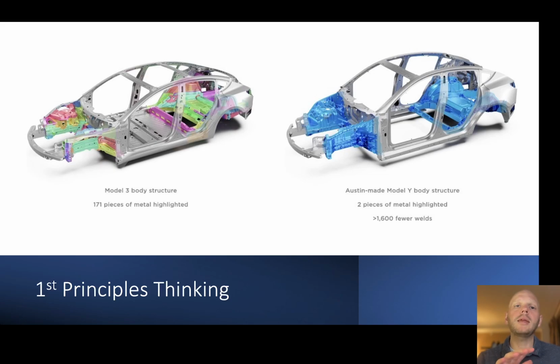And basically the way that most vehicles are manufactured is they have these stamping machines. They put a piece of flat steel in, a sheet of steel. They stamp it and it cuts and shapes the metal. And they have all of these individual pieces of metal, and then the robotic arms are going to weld all of these individual pieces of metal together into this structure.